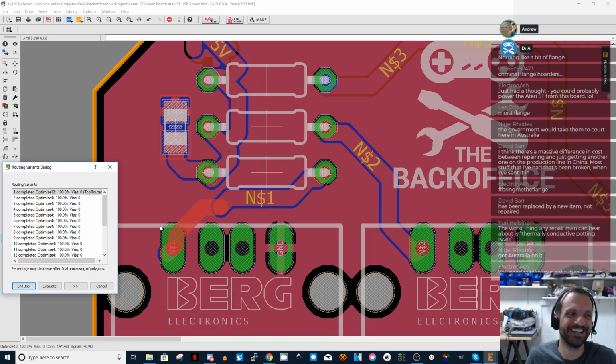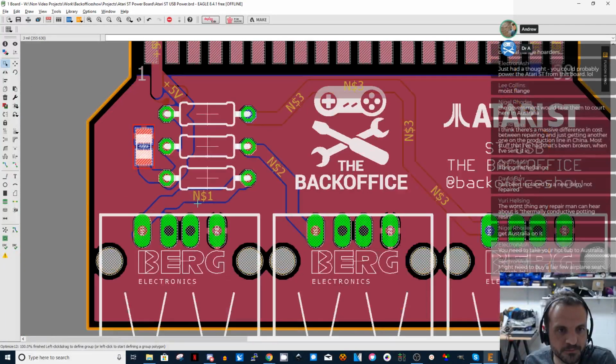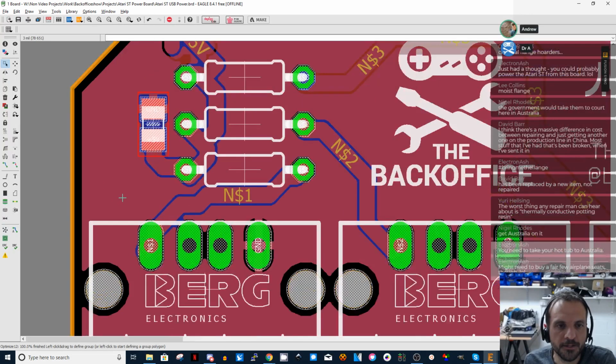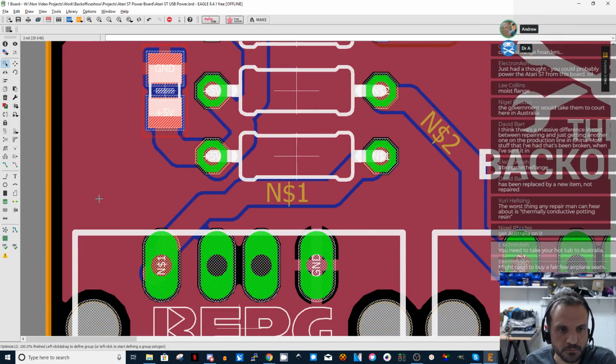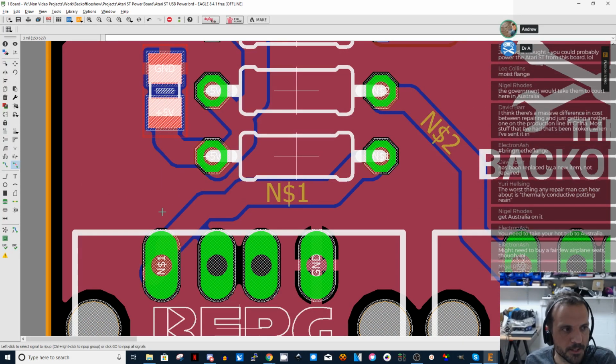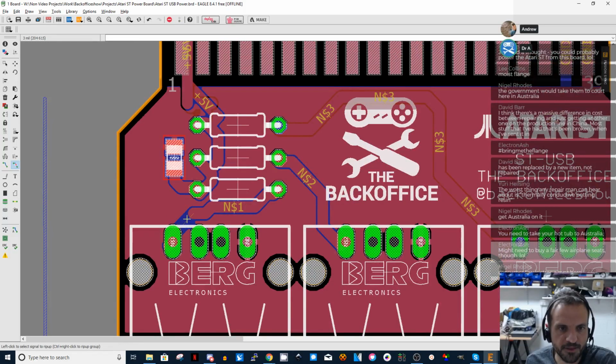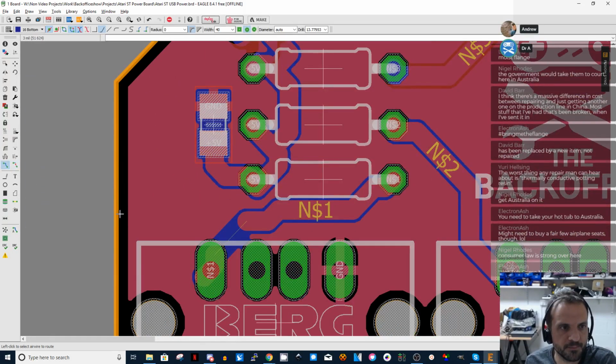No, but I just think it's a ridiculous situation that for the sake of what should be a very cheap item, the whole tub has to basically be replaced, because without the non-return valve, when the tub's full of water, it leaks back through the pump and all the water just pours out the bottom of the pump. I've got not a similar thing, but a thing that's annoying. I've got a Simmons coffee machine.